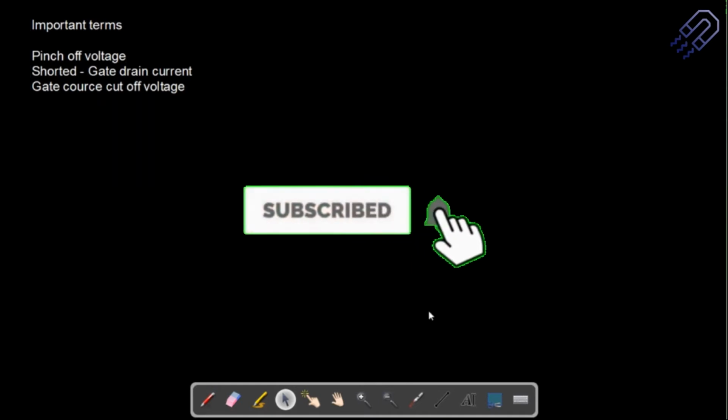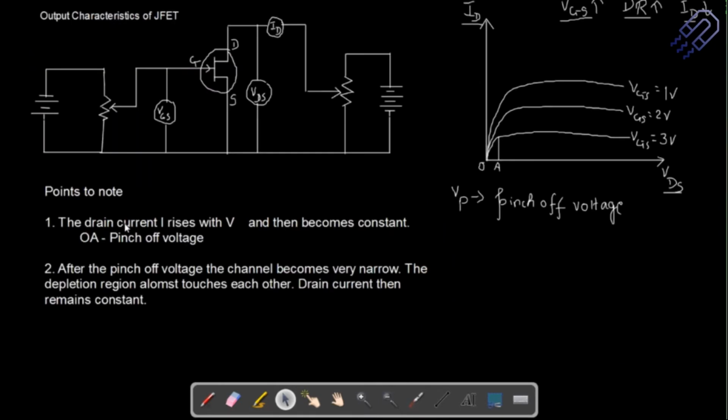So how do we denote it? Before that, I think I have just missed out the notation here. So this is ID, sorry. Okay, and then we are talking about the drain source voltage. The drain current ID rises with the drain source voltage. So this part will increase, this will also increase up to a certain point, and then it becomes constant.